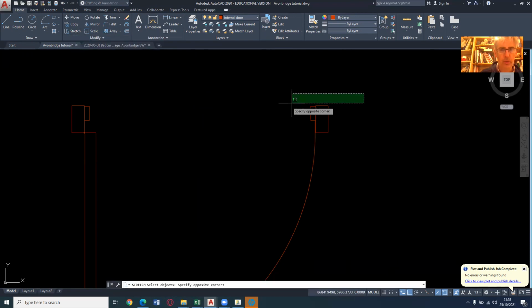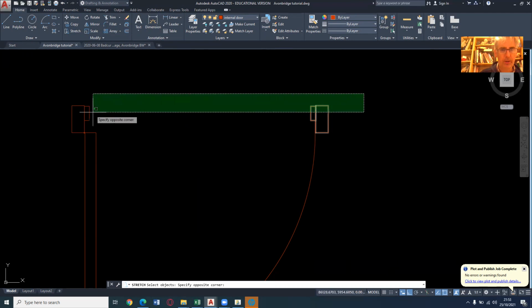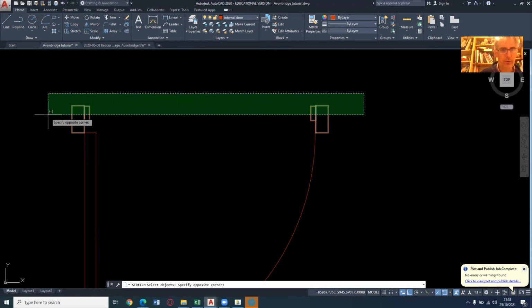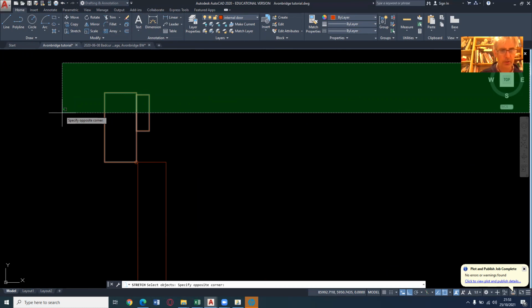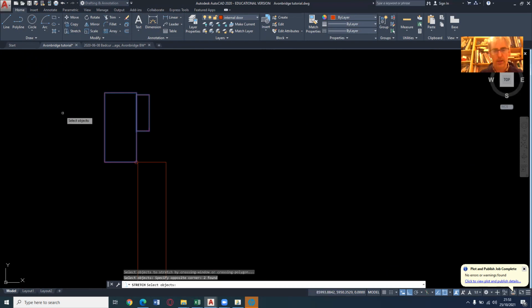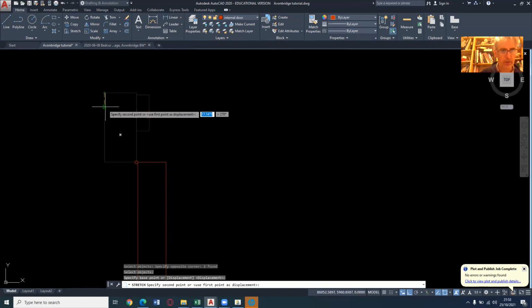I'm going to just swipe across this part, no further, but just around about there. In other words, you're going to try and contract this particular rectangle, or two rectangles in this case, and the other one's at the other side. You're going to use this as your control point, and drag it down by 20. So from 95 down to 75.